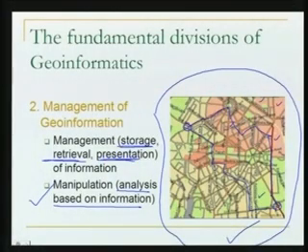So what we do in geoinformatics, we measure the geoinformation from the field. We measure it by recording the coordinates x, y, z, and we also identify the geoinformation that we have measured. Then we come to the office, we present the information, and we store it either in computers or in the form of maps, so that we can retrieve it later, present it in a proper way, and also analyze the information so that we can arrive at certain results.